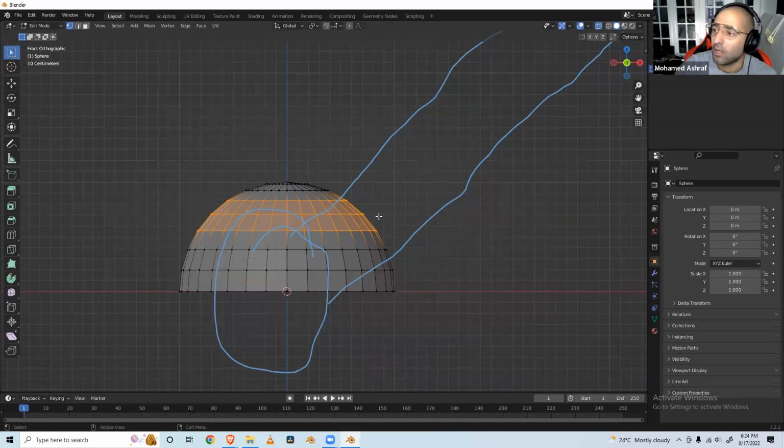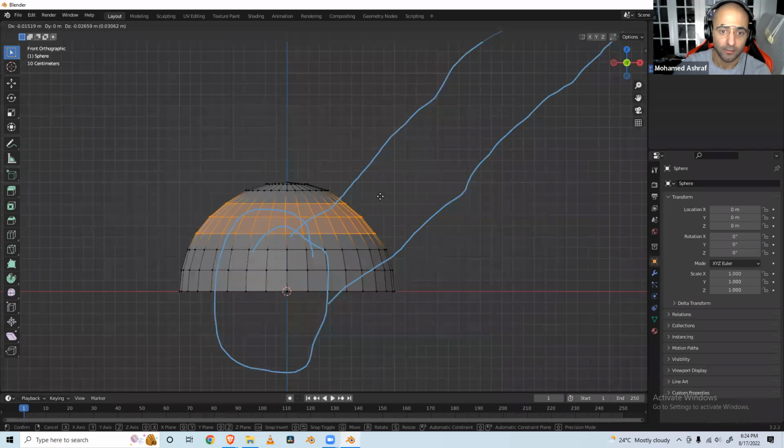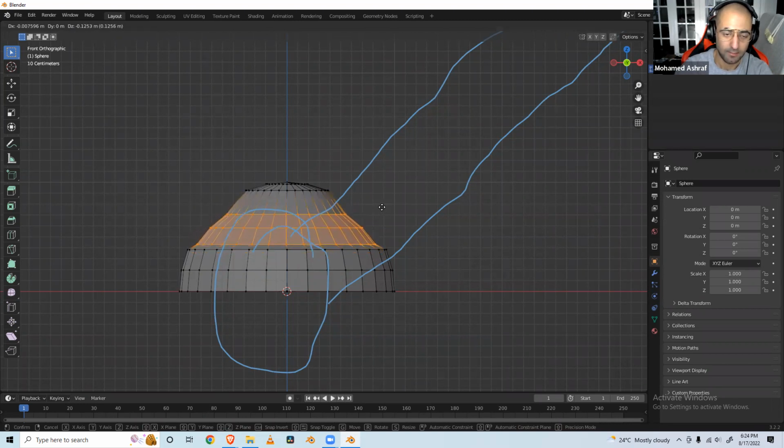And then we can actually get introduced to a very, very useful feature of Blender, which is the grab tool. Now, grab effectively means that you're grabbing whatever you're highlighting and you're moving within space. It's a transformation of coordinates. And if I press G for grab, you can see that Blender knows that I want to move these spaces. So let's say I grab and move down. You can see that it's a bit wobbly because it depends on my own mouse movements, and they're not perfect.